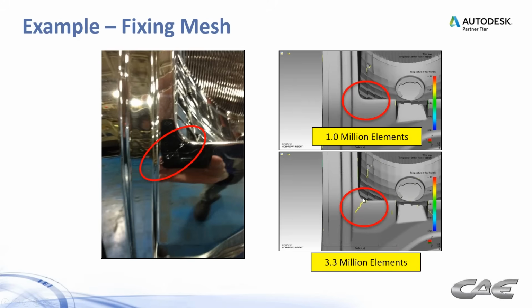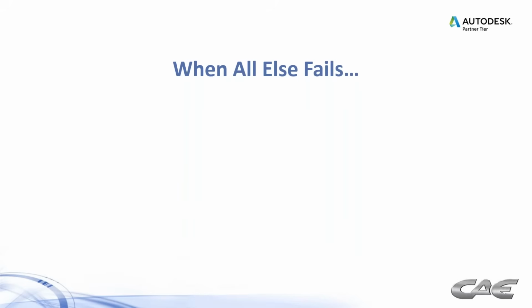So we were able to predict that knit line right where it occurred, and then offer some solutions to fix it. But one thing to note is that when you get into the situation, now you're a little bit handcuffed. There's only so much you can do once the tool's built to fix problems. You have a much wider range of solutions when the mold's not yet built, and you can change things to put into your design, whether it's the part design or the mold design.